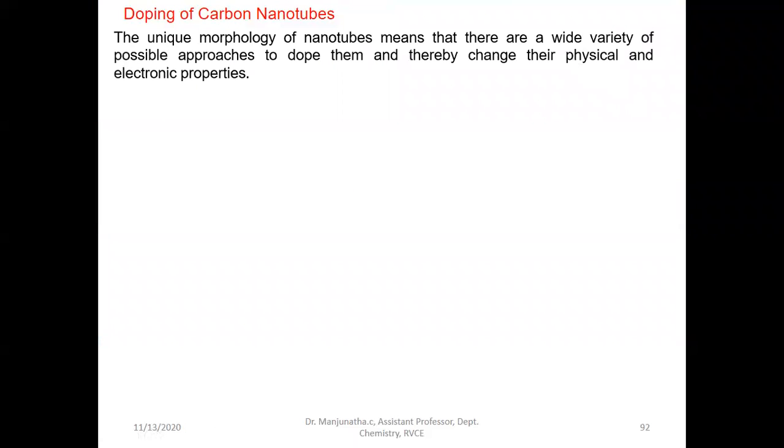We know that carbon nanotubes are one-dimensional materials, completely made up of sp2 hybridized carbon, rolled up in the form of cylindrical tubes. They may be made up of one-layer graphene or two-layer or multi-layer graphene sheets of different types, maybe chiral shaped, zigzag shaped, or armchair shaped.